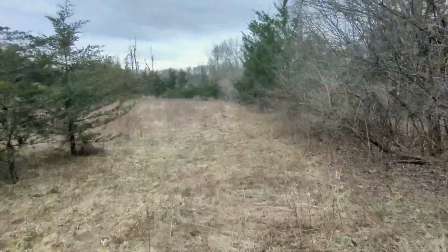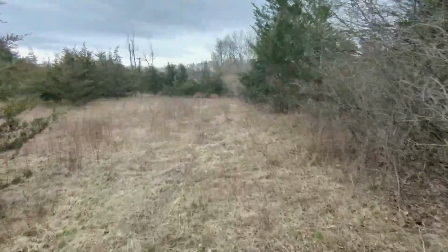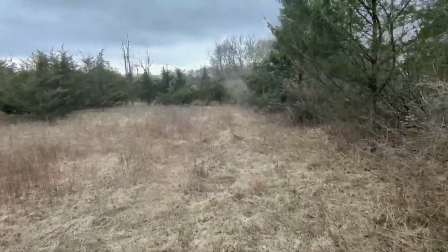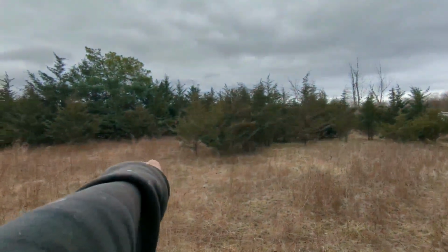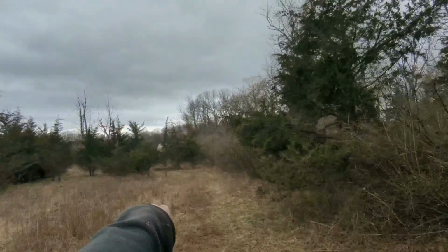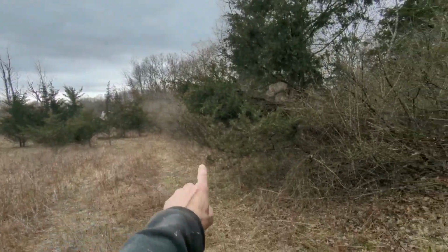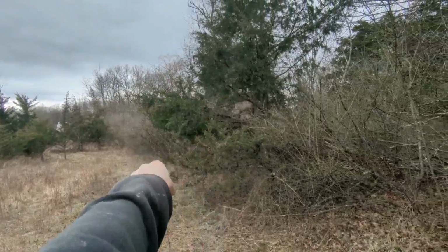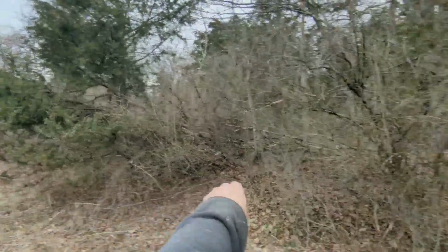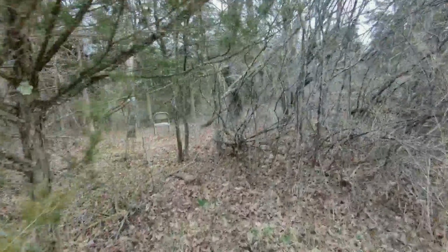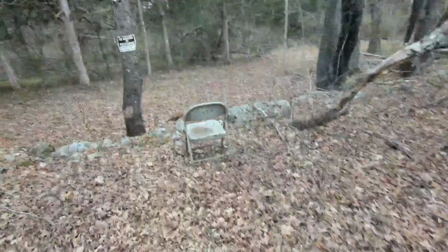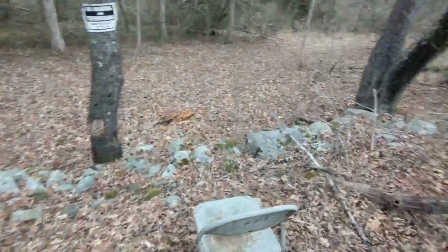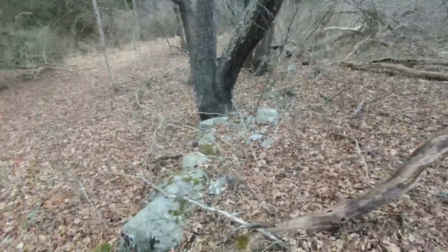Just backed off that eastern property line because it's so thick in there. I don't want to cross the property line trying to establish where it is. And we have a perfect corner point. We have a far south multiple corner points flagged, and along the side we have that corner point at the base or close to it. More importantly, we have a stone wall here. I have a feeling this is going to show up on our deed. Our stone wall and probably trees and corner points along this will be our property line.